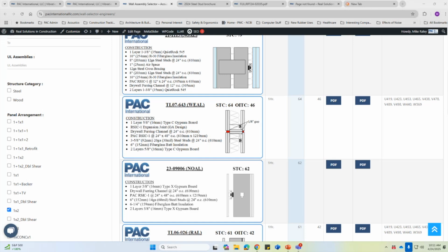Yeah. The point is we have no idea sometimes whether it's mineral wool or fiberglass and how much they could compress it. So I always try and show my details with a little bit of air, with most of the cavity filled with the fiberglass. Okay.